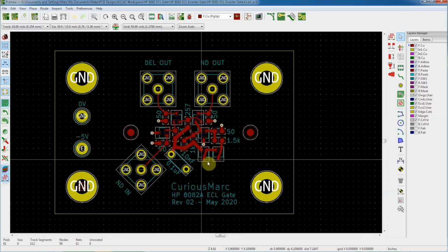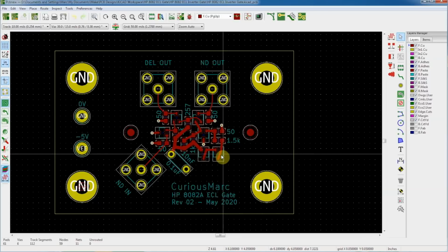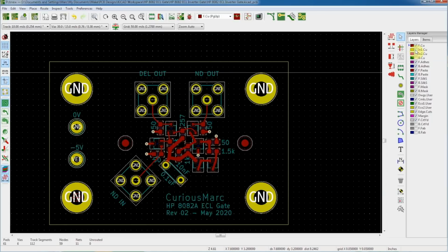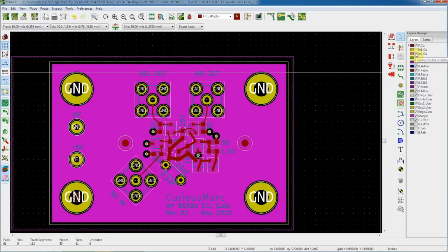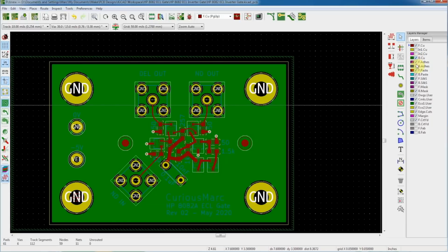Finally, the DC bias section is non-critical, so I put it down the corner back there. And besides the top layer, everything else is a pour, so here's the ground plane just underneath, so it's just ground everywhere, so there's going to be a well-behaved circuit with that much ground. Then I use the layer beneath that to do the -5 volts, and I added a capacitor for good measure. And the last layer had one layer too many, so I just put another ground there. So that's it.